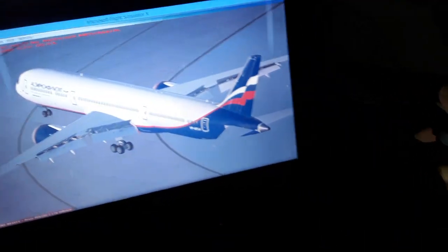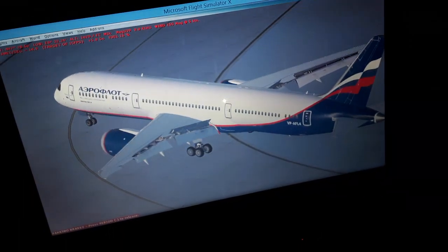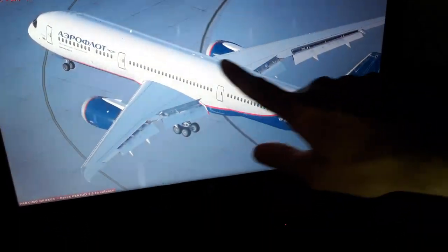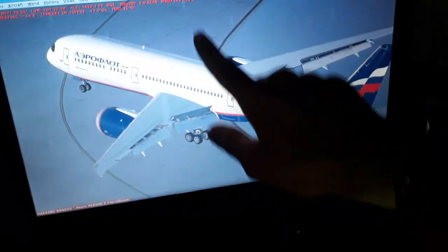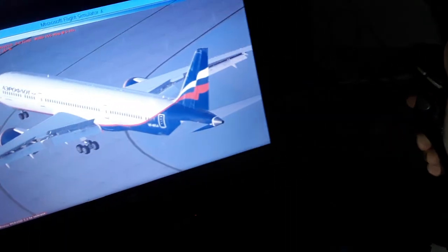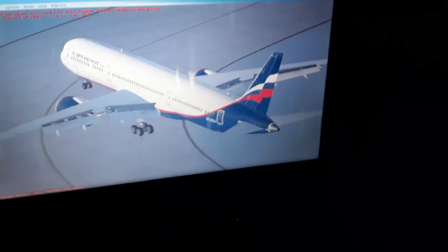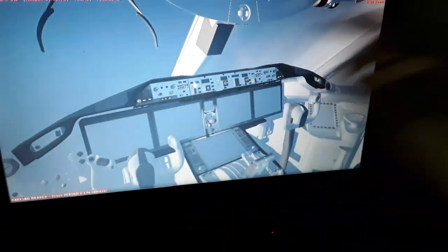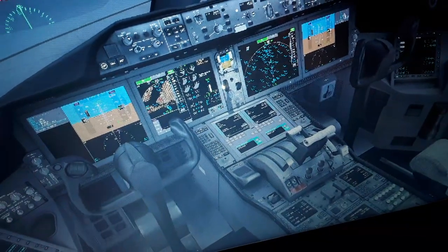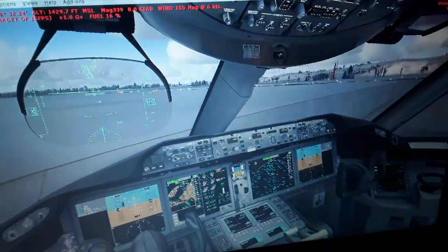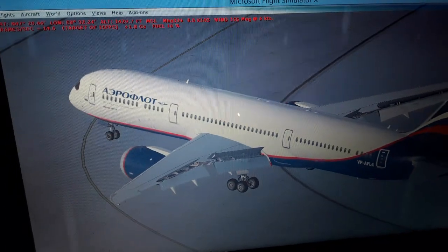So you can see here, also we have the aerodynamic chord position. This is the vertical axis, where the center of gravity is, so we can control the yawing axis using the rudder pedals like this. I have the side stick, and the yawing axis of the aircraft, the rudder, which is also controlled using the rudder pedals. I show you inside, over here you can see the rudder pedals. So it's left and right rudder pedals, also the nose wheel steering over here, the tiller. So the rudder pedals are interconnected with the tiller and with the nose wheel steering.